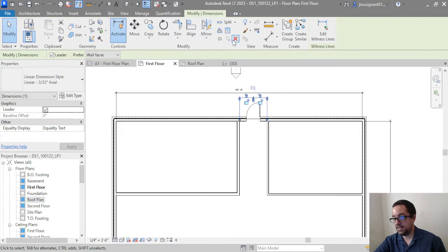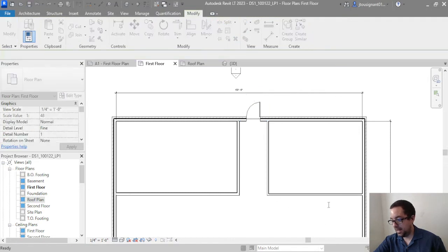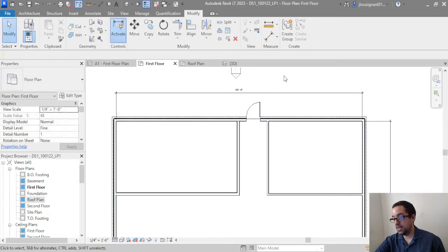I can even take this and delete it, and it's going to say I did that equal tool thing, and if I click OK, it's going to stay equalized, or I can unconstrain it, and then it gets rid of that equalize and the dimension. So I'm just going to click OK because I want it to keep that constraint while not being in my way and telling me it's in the way.